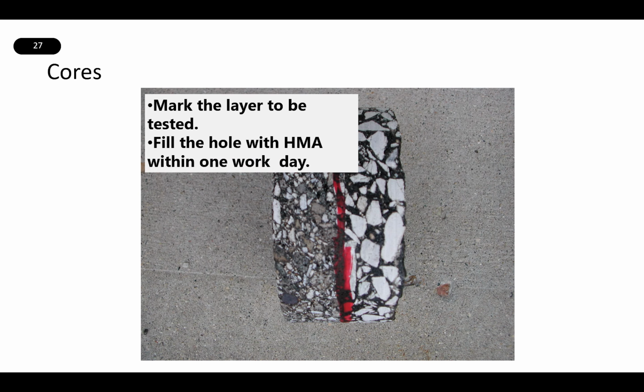If it's a full depth core, once the core is removed, clearly mark the layer that is to be tested. Then take the core and place it in a plastic cylinder with a lid to allow safe transport to the testing facility.